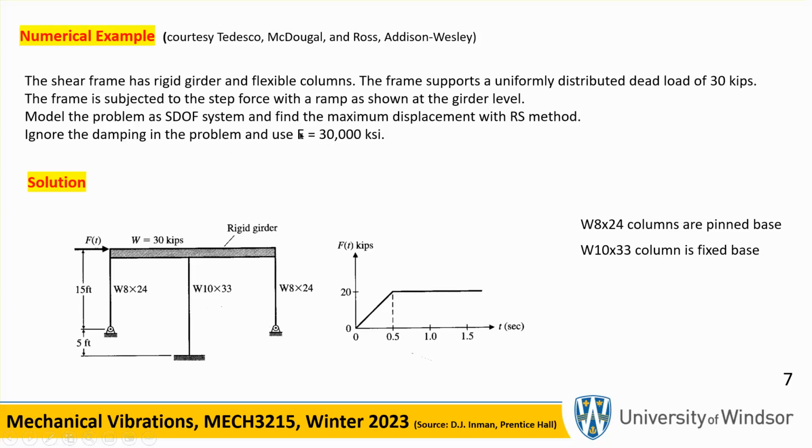We are assuming that the Young's modulus is given as this, it is steel, 30,000 KSI. By the way, KSI means 1,000 PSI. We'll come to what I want to talk about as far as the other unit in a minute. KSI means 1,000 PSI, so that's 30 million PSI Young's modulus of steel.